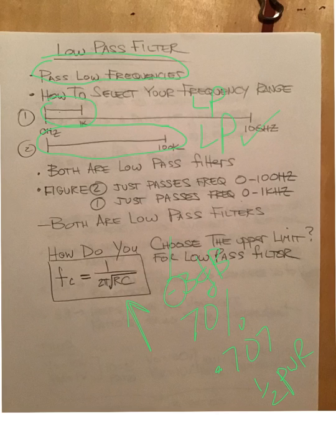The minus meaning that the signal has gone down from 100% to 70%. That's a drop. So this is the equation. It's just 1 over 2 pi square root of the resistor and the capacitor. They both have to be in base units: the resistance has to be in ohms, the capacitance needs to be in farads. More on that shortly.